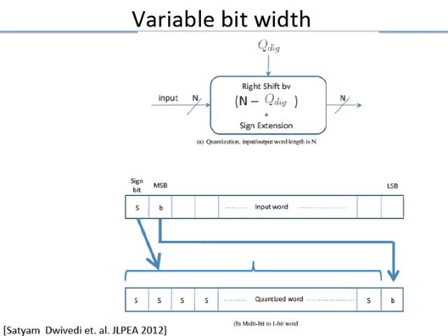In signal processing systems, you're processing the data, you're applying some algorithms and transformations on the data. Now you know that that data is a digital representation of some physical signal. A physical signal is analog, and whenever you capture it in the digital world, you are going to use some number of bits. As soon as you use a finite number of bits, you have what is called quantization noise.